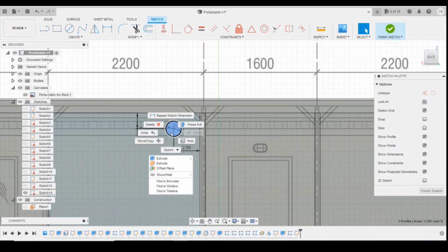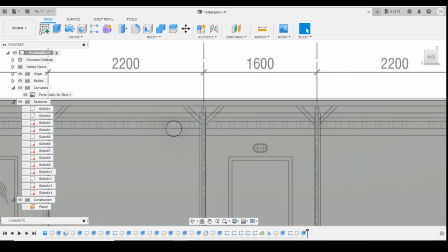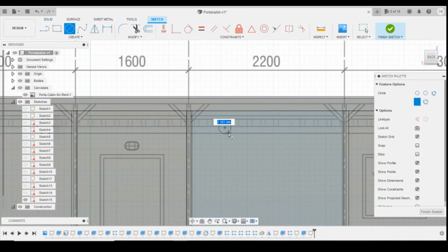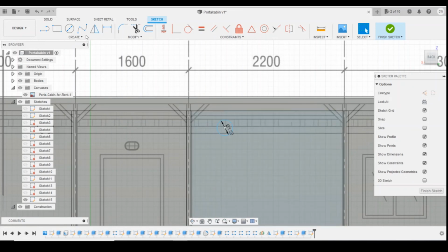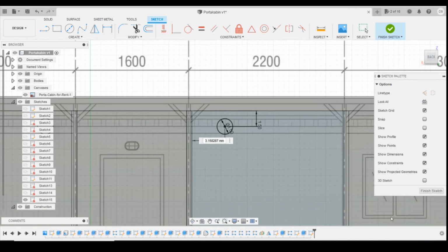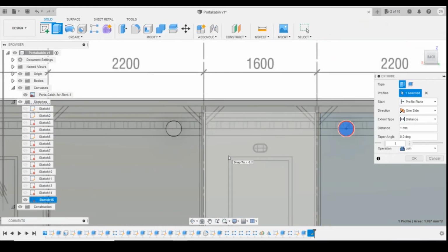And as we're just looking at a vent type thing, we're just going to extrude that forward slightly. It's going to come forward 1mm to give that relief that we're looking for, and then we'll just draw the same over on the other side. Making sure those measurements are the same, and again extruding it forwards about 1mm.